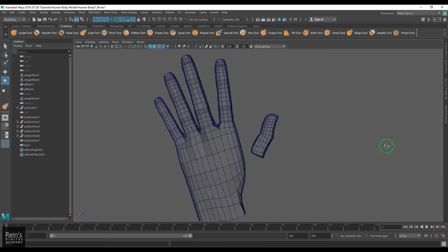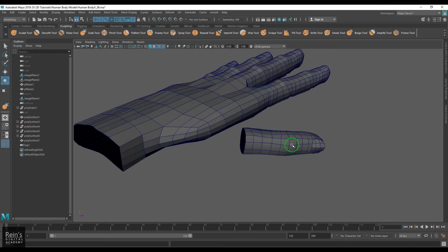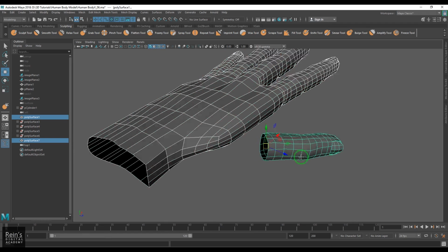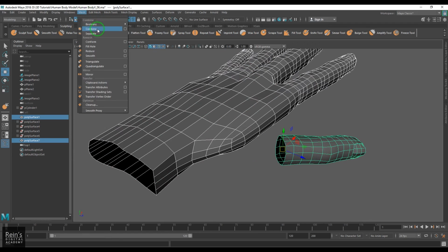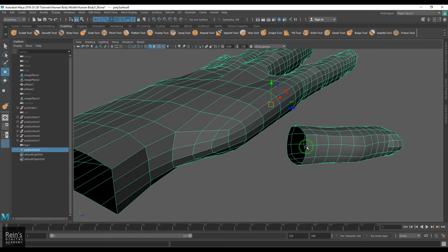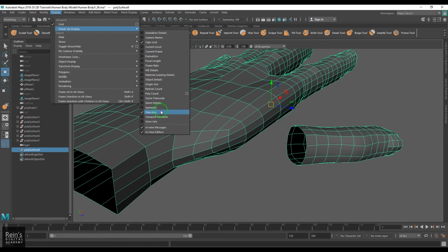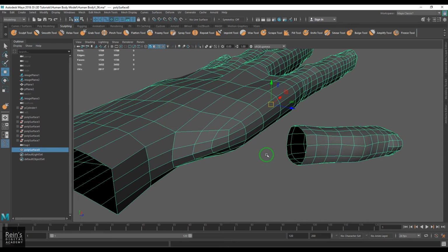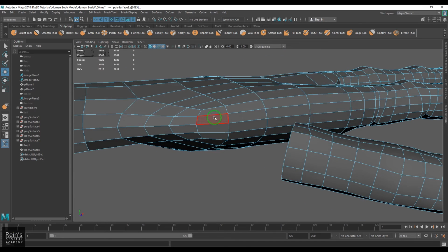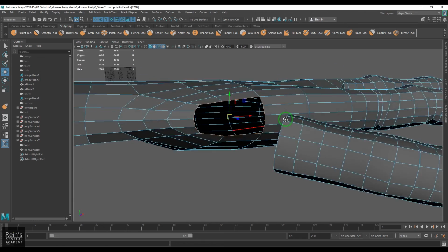just giving a little bit of bend or curl, and then select both of them and then apply combine, and just select the border edges and see how many border edges are there. For that I go to the heads up display and then choose the polygon count, and then select the border edge, and then you should be able to see there are 14 sides. So let me try to delete all these faces here, and then see the border edges here. It's 12. I need to get 2 more.